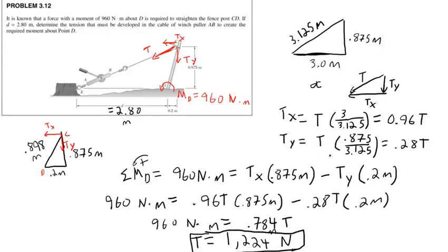So, questions on that? All distances are positive? Yeah. Okay, so in this case, I don't need to worry about putting a positive or negative sign on the distance, because I'm looking at this and actually applying a positive or negative to the entire moment. That's when you're doing this. If you're actually finding the vectors directly and doing cross products, then you'll need to worry about that. But for simple 2D systems, I prefer just to eyeball it and say, okay, this one's positive, this one's negative. You'll find that often it's a lot simpler.